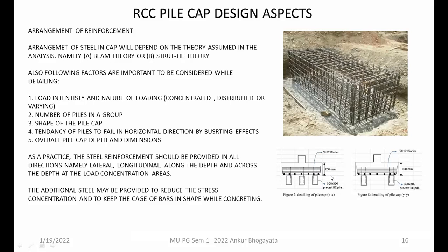So take this advice as your thumb rule whenever you are designing any RCC element: if the thickness of any of the RCC components crosses the limit of 400 mm, or let us say 300 mm ideally, then provide some minimum amount of steel in the opposite direction also.